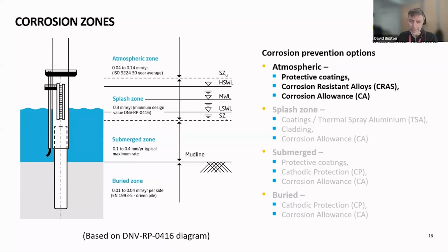It's corrosive, especially to unprotected steel, and to ensure the continued safe operation of offshore assets, corrosion and the management of the corrosion is essential to ensure safe and effective operation. Generally it's the supply of oxygen to the steel surface that drives the corrosion, and then the presence of the chloride in the marine environment increases the corrosivity.